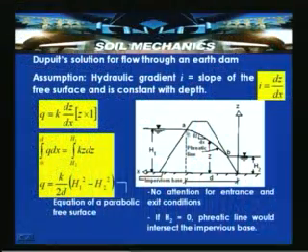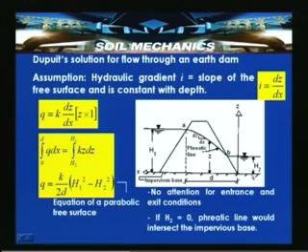So, Dupuit assumes that this phreatic surface is a parabolic free surface, but Dupuit's solution has some limitations. No attention has been paid to the entrance and exit conditions. For example, here this is an equipotential line, where the orthogonality required between it and the flow line, that is the top phreatic surface, is not maintained. Similarly, at the exit conditions a similar phenomenon arises. And if H2 is equal to 0, the phreatic surface would intersect the impervious base, which is itself a flow line. That cannot happen. So, these are some of the limitations of Dupuit's solution.